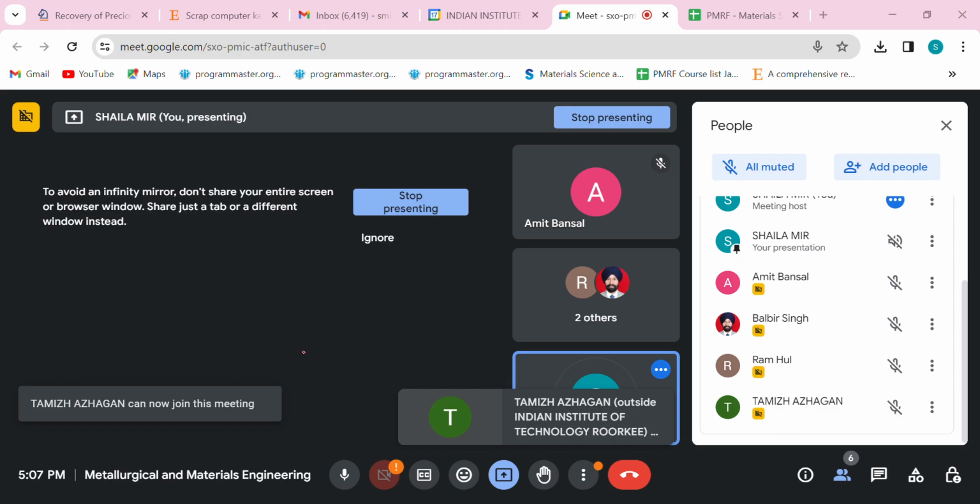So you have to find the modulus of your composite. The modulus of your composite will be equal to the modulus of your matrix times the volume fraction of your matrix, plus the modulus of your fiber times the volume fraction of your fiber, right? The matrix here is aluminium, so its modulus is 69, and the volume fraction of your matrix will be 0.6, because we know the total fraction will be 1.